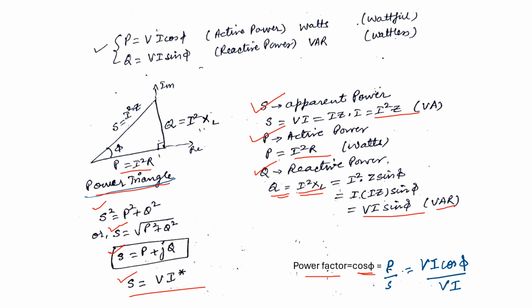So the apparent power, we can see from this power triangle, is the vector sum of the real power and reactive power. It is a very important quantity, the apparent power, since AC apparatus such as generators and transformers is usually rated in volt amperes rather than in watts.